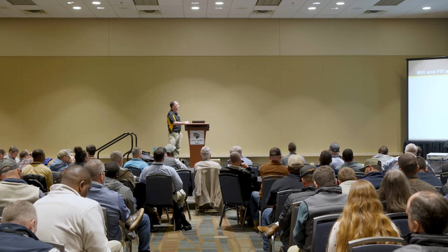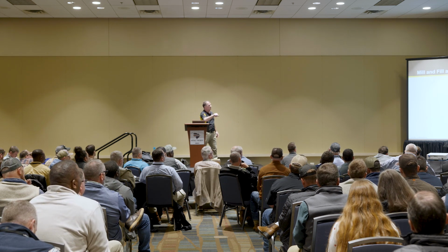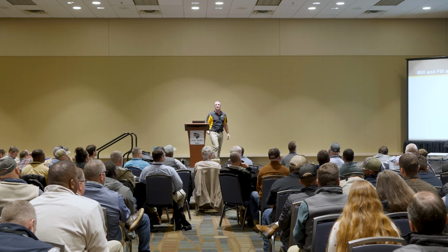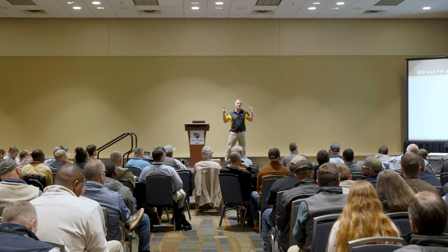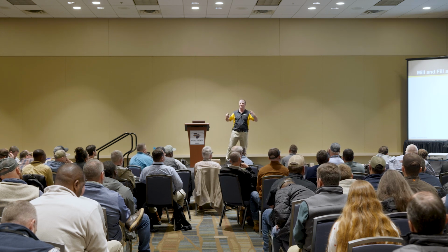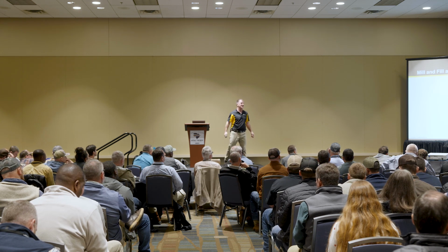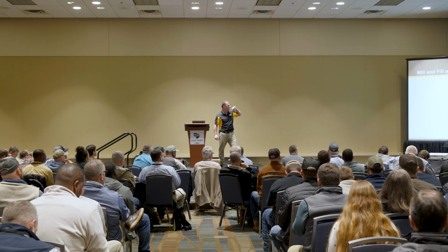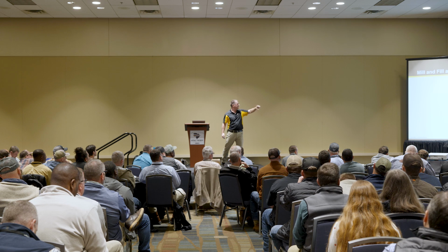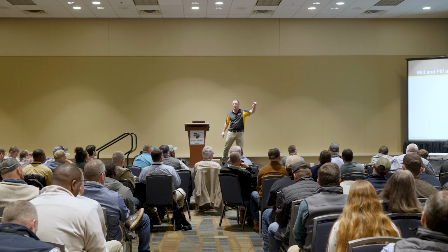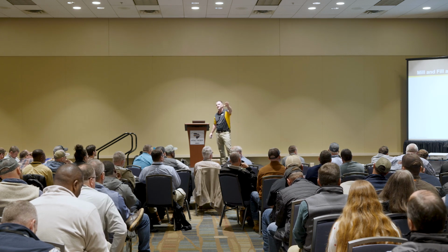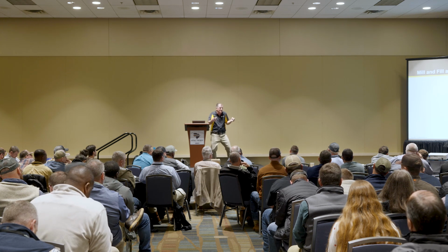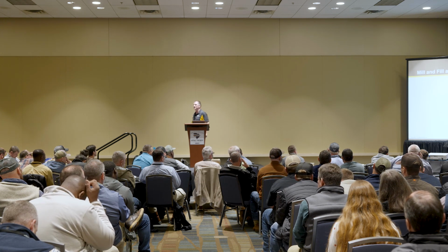But what problem do you see going on here now? It's not uniform thickness all the way across, right? What do we have to do with that mix after we pave it? Compact it, right? We got to roll it. How much does that mix roll down? Quarter inch per inch, right? So in those thicker areas, it's going to roll down more. Am I going to have 2% all the way across? Probably, maybe. If I got a good roller operator that straddles that shoulder break there.